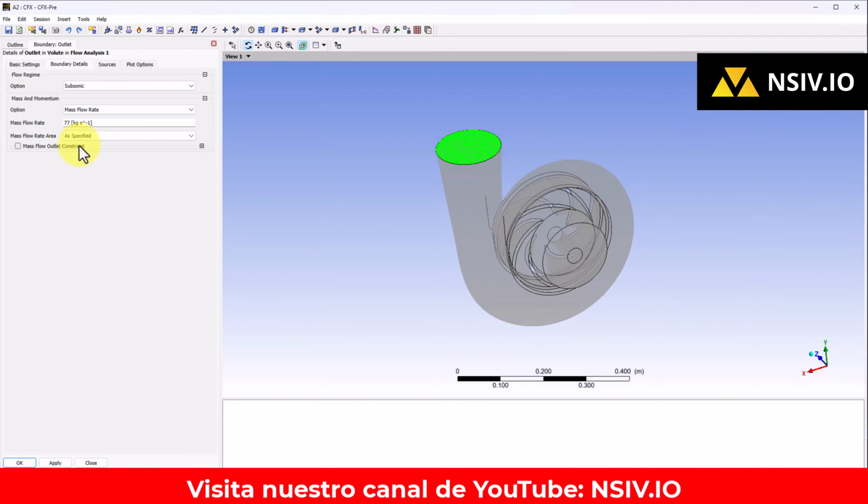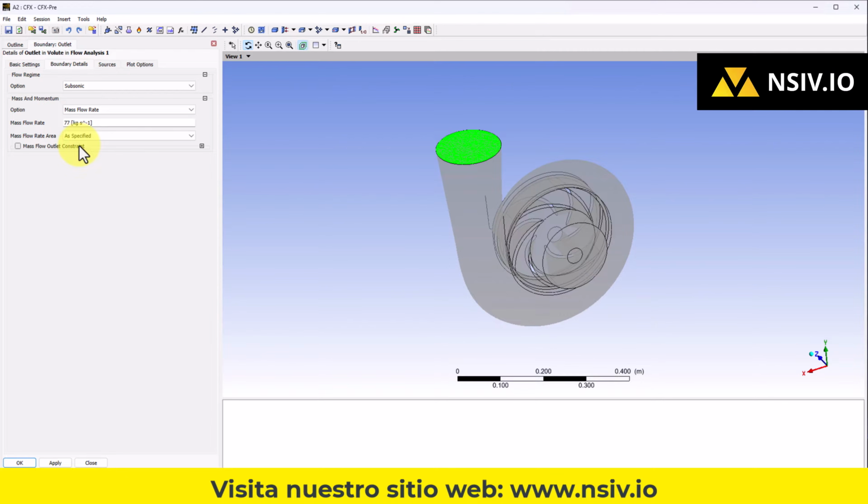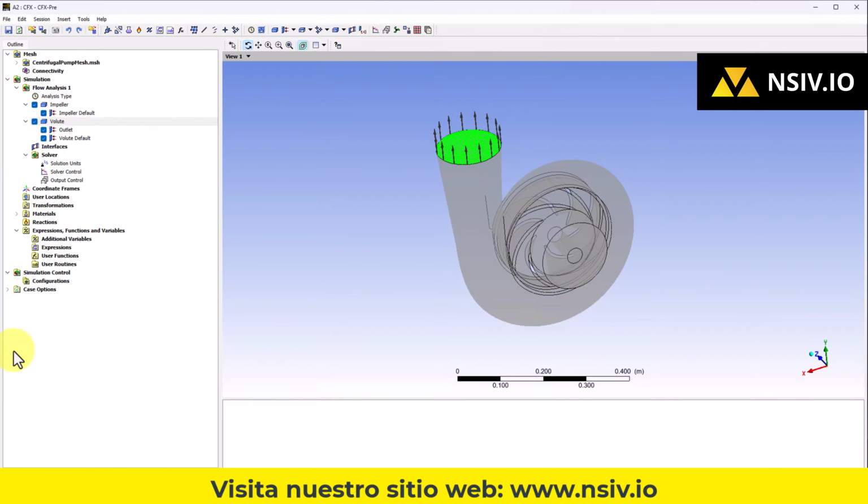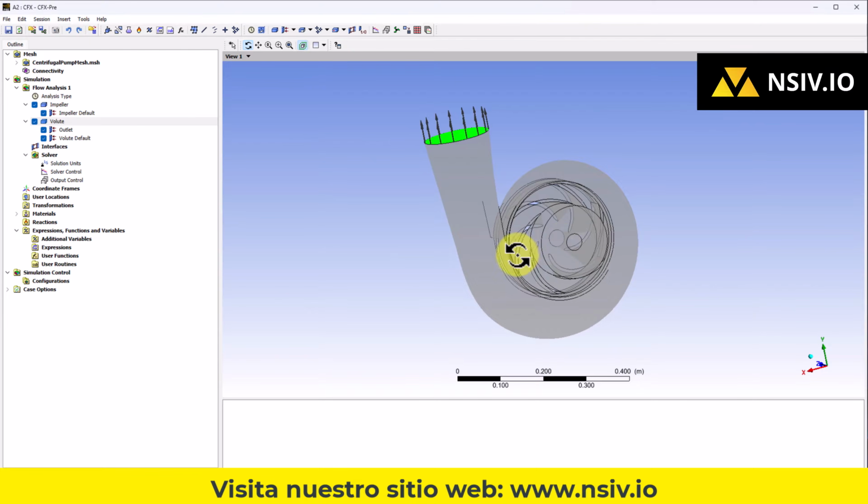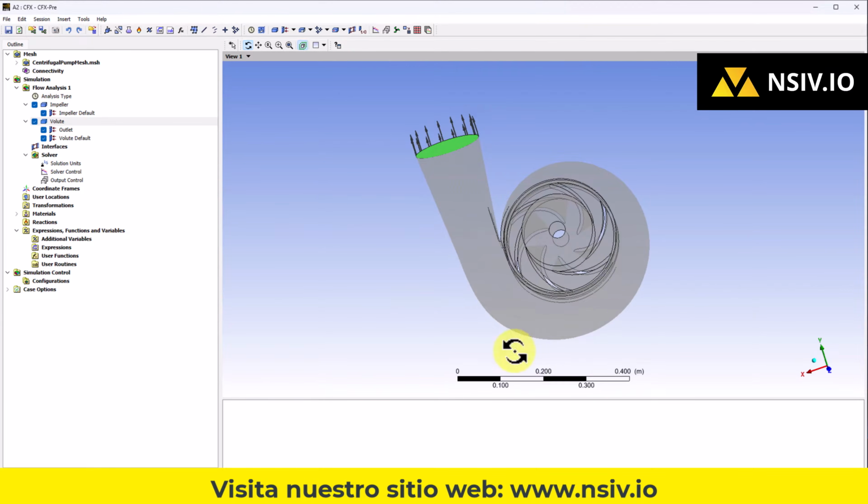Remember, for scale issues, for geometry issues, for calculation issues, you can work with the pump that you have designed by modifying the values of both pressure and flow, or guide yourself also from some characteristic curve as you see fit. I'm going to apply it and then OK, perfect. Then what else do we have here? In the volute we have the wall condition.